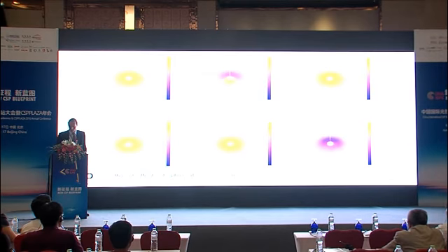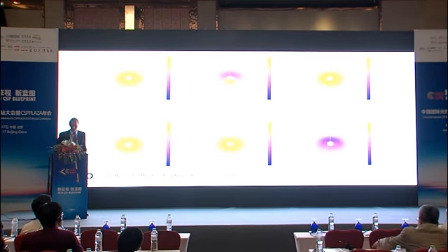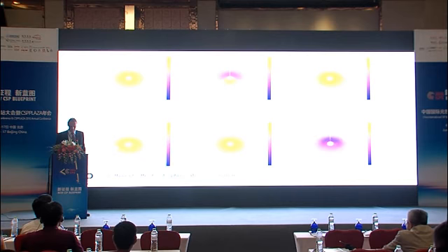Then you have the atmospheric attenuation. You can see the losses in here. Around the tower, nearly no losses because the distances are small, and if you think about 1.5 kilometers, you get up to 8% of sun radiation losses for a very good site, which might be completely different in China. So here we can see the losses by shading, the losses by blocking, and the overall total efficiency on the plant, if you do your TMY calculation over 1 year. That's the overall efficiency which is calculated and optimized.